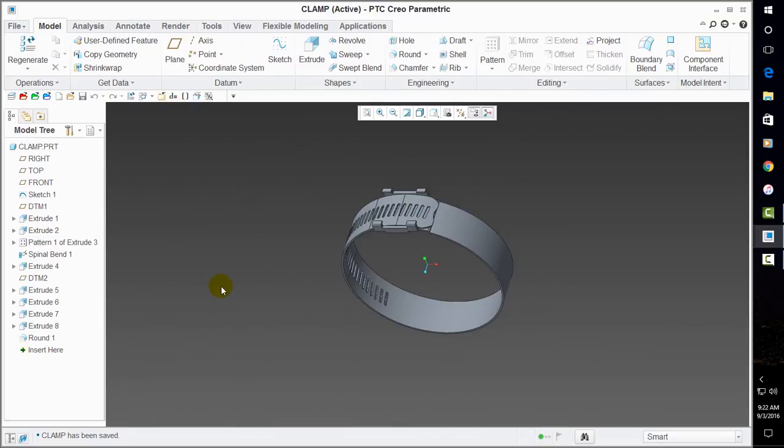And now we're ready to import our two components. Now you can make an assembly out of this, or you can make it one part. I'm going to do it as one part. Easier to do the relations to get things to work better with that screw. If you don't need that screw to rotate like it is in a demo, that's fine. You can make it an assembly. It's just a little bit trickier if I do it in assembly to get that screw to turn. It's super easy to do it if I do it at the part level, so I'm going to stick with that route. If you don't need the screw to turn, you're not going to put that much detail into it.